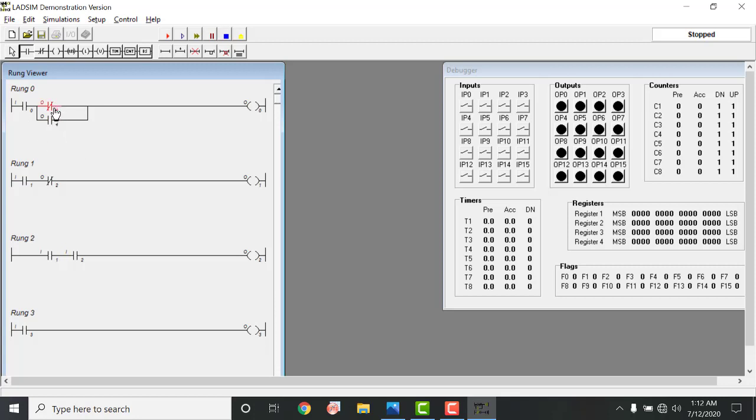For example, the infrared sensor is detecting output information. So this is used as a continuous ongoing. When this infrared sensor detects the limit reached, it would open this normally closed switch and the system is running. But after the timing completes for 5 seconds, we will receive our information at the output 4. So that output 4 will send this information over here and it will complete the signal, and again we can run our system. So let's start with the simulation.